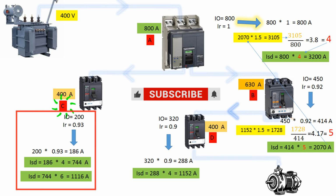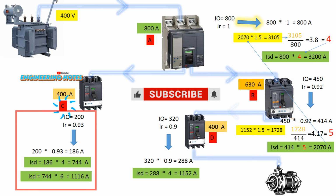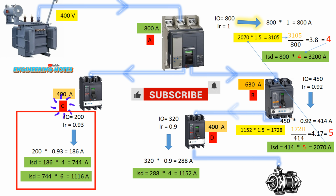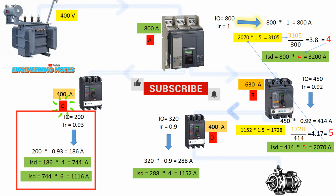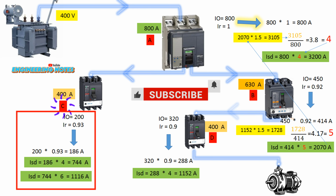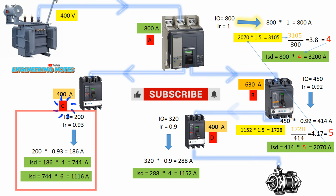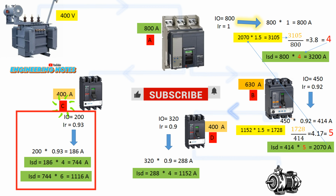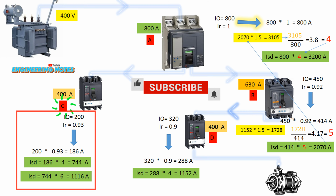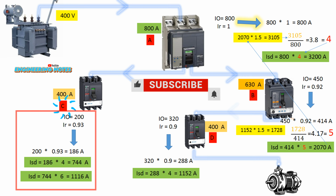For the last breaker, breaker C, if we set the ISD range to 4, then by multiplying 4 by 186, we obtain a value of 744. We can even set the ISD range to 6, which gives us 1116 when multiplied by 186. This is also acceptable, because it is 1/3 of the short circuit setting of breaker A, and therefore no coordination problem occurs.